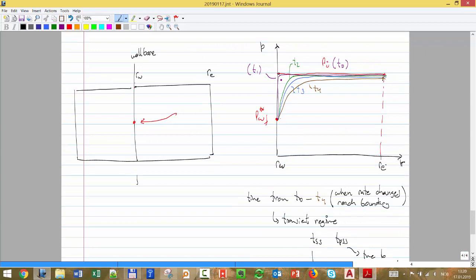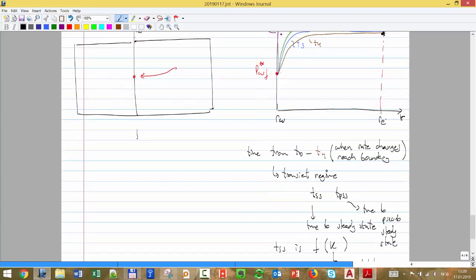After that happens, you have two options. One of the options is that pressure at the boundary is somehow kept constant. That can happen if, for example, you see the well from the top: you have one well, an oil producer, and then another well where you are injecting, let's say water injection. Here you have a water injector, and that's this r_e. So with this injection, I'm keeping that pressure always constant.